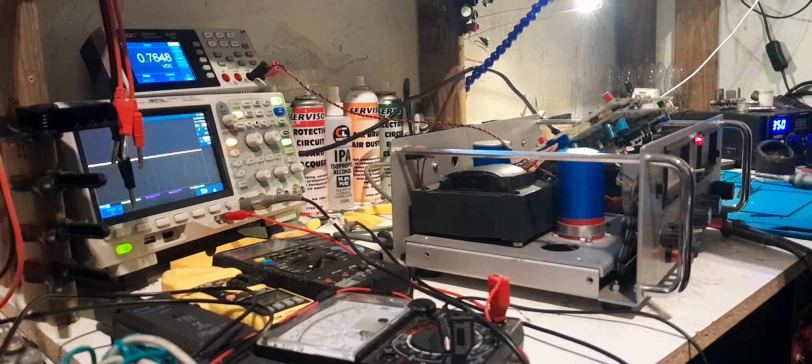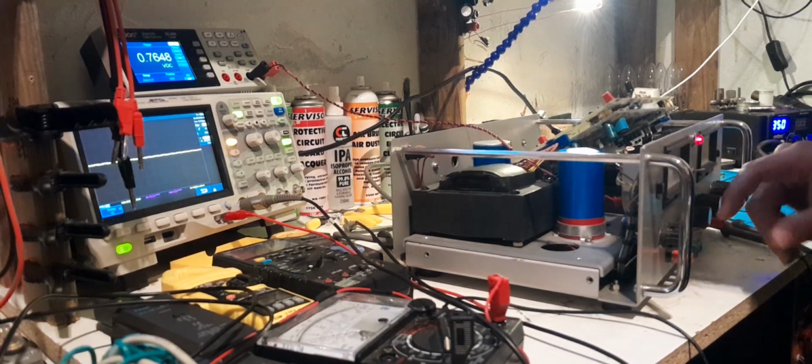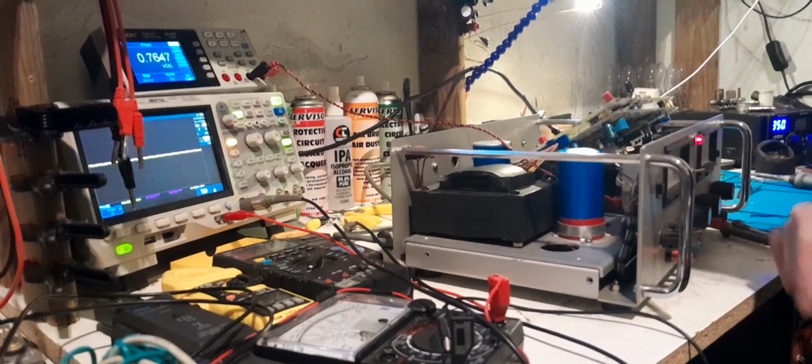It's too noisy and panel meters were oscillating, so I'm held up on that at the moment. But the current section in that, what I've done is I've got a current sense resistor on the positive rail, with an op amp looking at that.